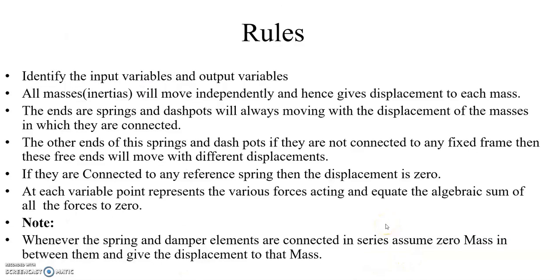Next are the rules you have to follow when writing equations for a mechanical translational or rotational system. First, identify the input variables and output variables. Next, all masses, or moments of inertia, move independently and hence give a displacement to each mass. The ends of springs and dashpots always move with the displacement of the masses to which they are connected.